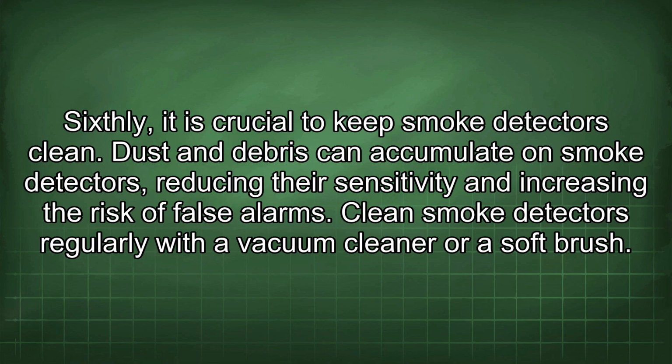Dust and debris can accumulate on smoke detectors, reducing their sensitivity and increasing the risk of false alarms. Clean smoke detectors regularly with a vacuum cleaner or soft brush.